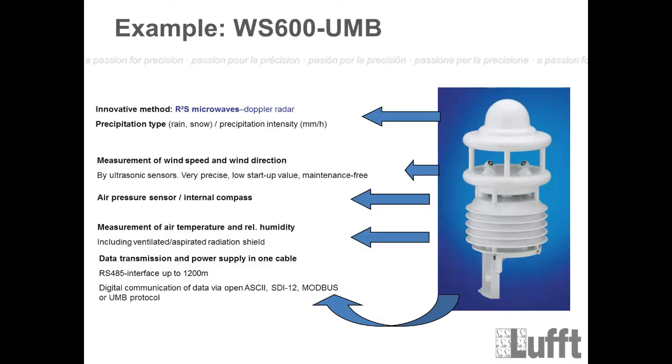Alright, so at the end we have also the communication, and I told you that we normally have RS485 communication type for all the WS sensors. With this communication interface you will be able to communicate without any amplifier with a length of 1200 meters. But that's only information for the two communication wires. We are not talking about power supply.